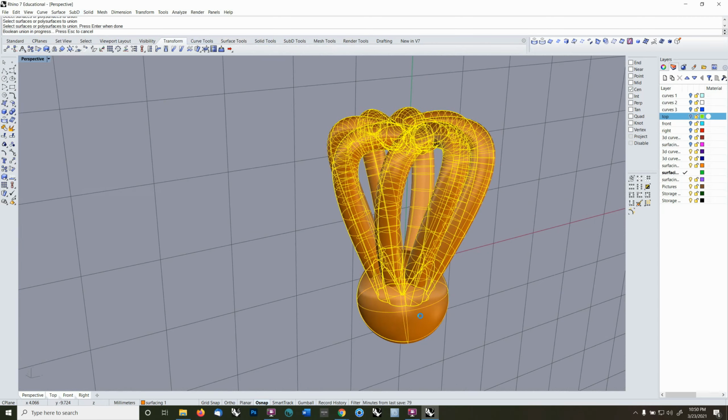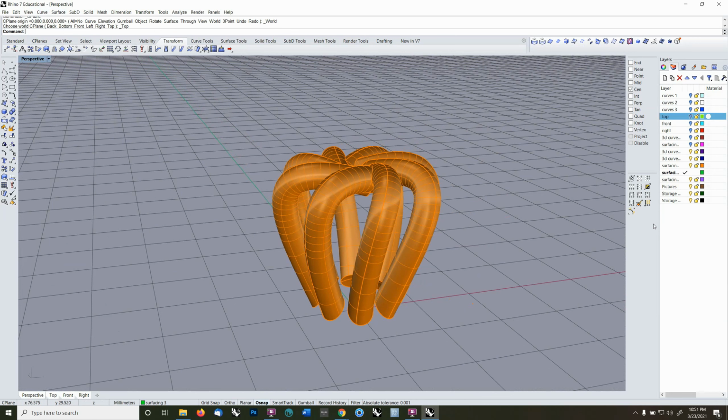Now, Rhino will keep telling you that you can use a surface to do Booleans with. You really cannot. Okay? The only Boolean function that works well predictably with a surface is difference. Boolean difference, cutting. And I'll say it again and again, in CAD modeling, the main thing you want is predictability. So even though you might be able to get an intersection to work with a surface, first off, you're going to get an open polysurface. It won't be a solid when you're done. It's a dead end. But also the results will be unpredictable.